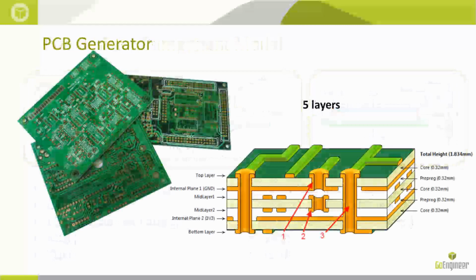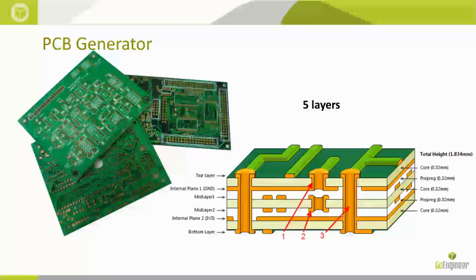Another one is the PCB layer. Again, in most cases, you're not going to be making the PCB yourself. So as long as you know the amount of dielectric constant, as long as you know the amount of conductive material in there, let's say you have 5 layers, 10 layers, 50 layers, as some of the boards have these days, you would get an equivalent thermal conductivity value for that PCB using the PCB generator tool. And what that does is it helps you get a good understanding of the thermal profile without going into all the nitty-gritty details of what it does.